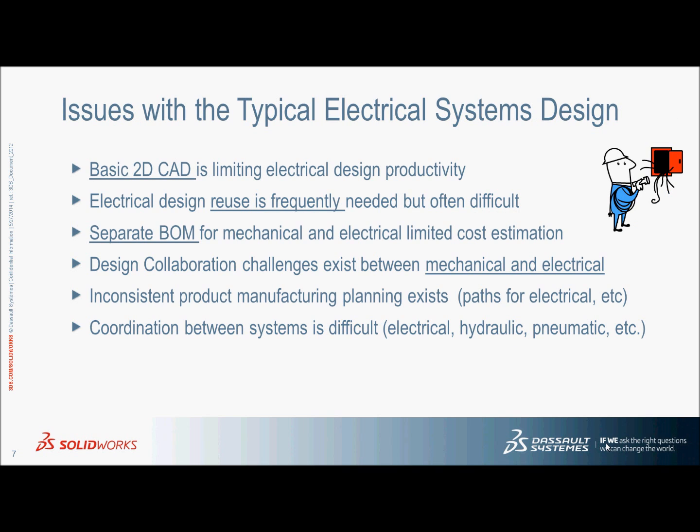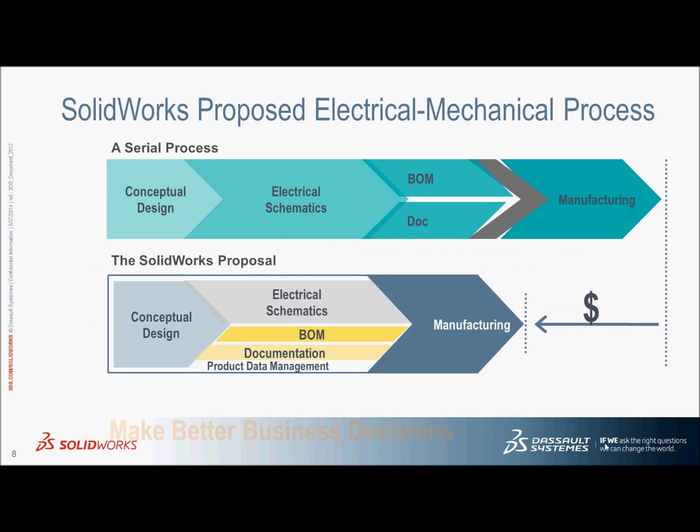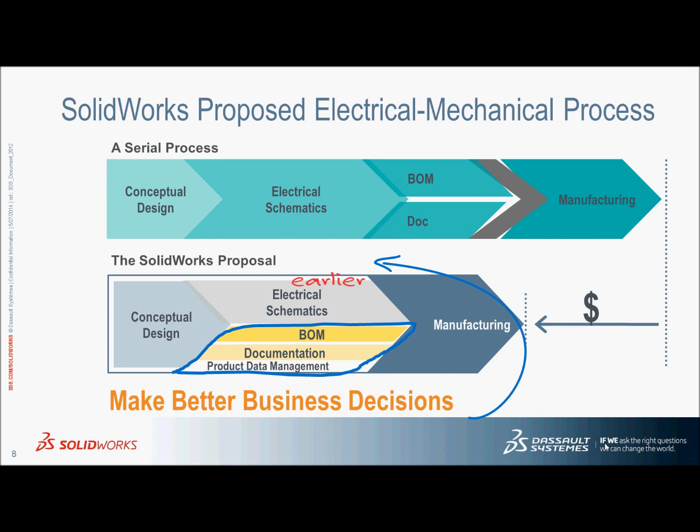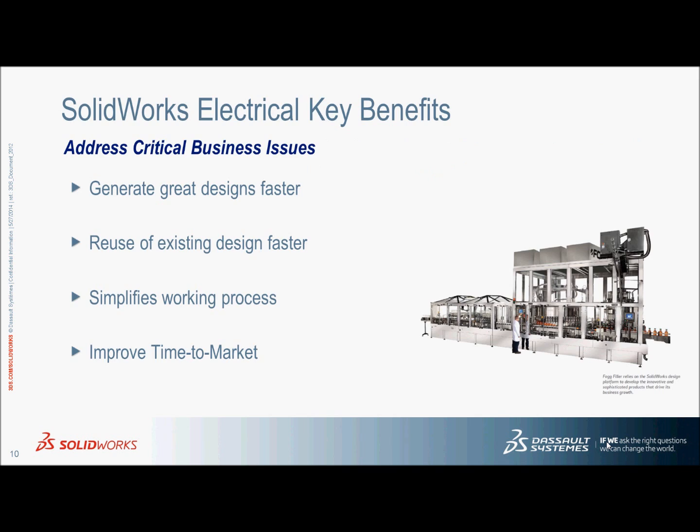A common issue engineers and designers face while working with 2D CAD is that reuse of previous designs is often not friendly and requires a lot of re-editing. The BOM needs to be manually updated, which often causes human errors. With this, you can have an earlier market time. In SolidWorks Electrical, as mentioned earlier, the user works under real-time bidirectional integration, which also means any changes made will be automatically updated to all the related references. This will help you generate your design faster and simplify the work procedures.